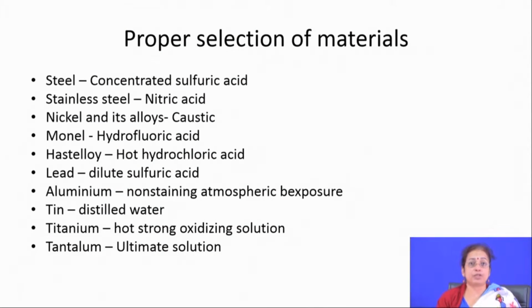So, these are the guidelines which you must follow for preventing or minimizing the probability of different types of corrosion. Now, if you talk about proper selection of materials, especially for aqueous corrosion based problems, you will find that different materials behave differently, and these charts give you guidelines about which material will not corrode in a particular environment, particularly when this is the case for general corrosion. Because for stress corrosion cracking we saw a separate list, for liquid metal embrittlement we saw a separate list.